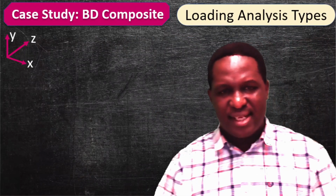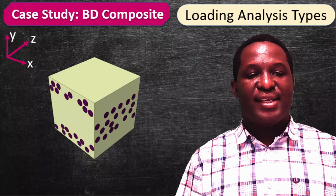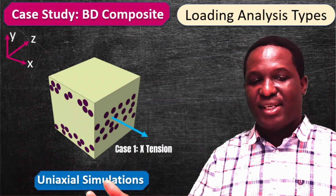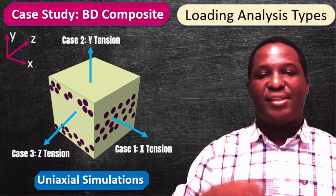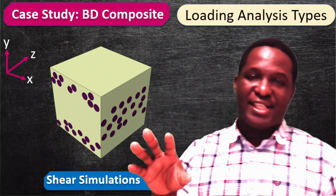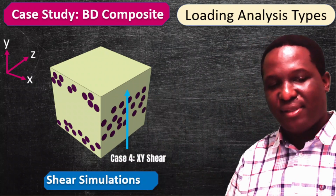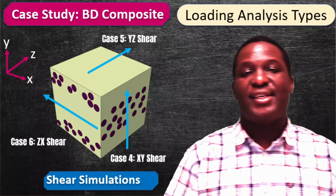Now, in terms of the loading analysis, which is basically the case studies, the simulations that we're going to run for this. If this is our RVE, we want to first do a bulk of uniaxial simulations, of which we'll have case 1, where loading is in the x-axis, case 2, loading is in the y-axis, and case 3, where loading is in the z-axis. So these are the 3 uniaxial simulations, and of course we'll also have shear simulations, just to show the depth of what this RVE modeling can give to us. And so we'll also have a shear deformation on the XY plane, a shear deformation on the YZ plane, and a shear deformation on the ZX plane.